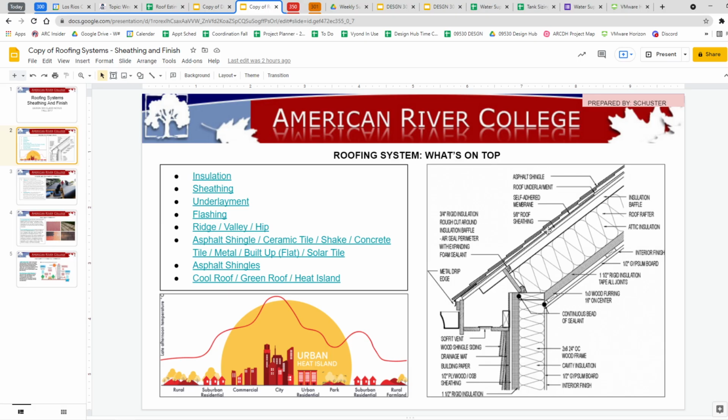Now, asphalt shingle does provide waterproofing, but it's really tough. It's meant to be a protective layer for your underlayment and your self-adhered membrane that really keep the water out. Water can seep in, you can lose a shingle, they can get damaged, and especially at edges they can leak a little bit, and you've got nails through them.